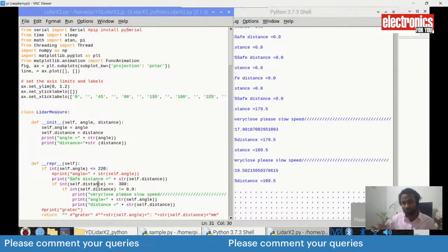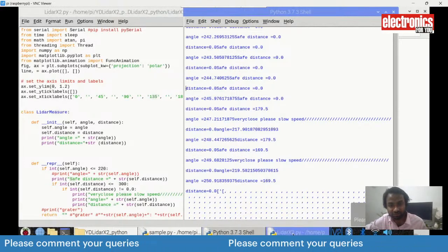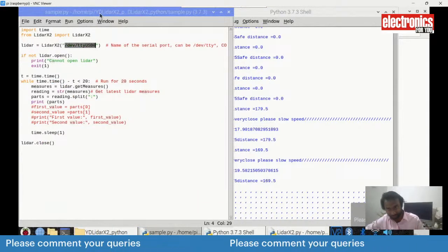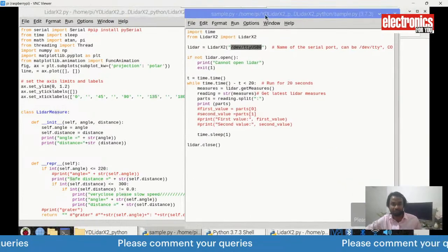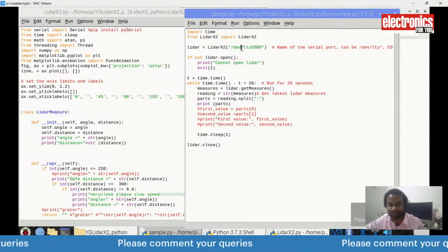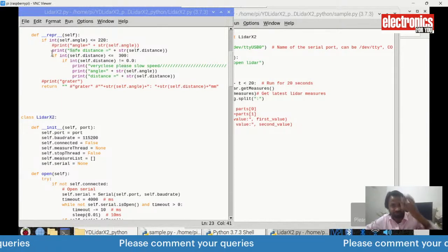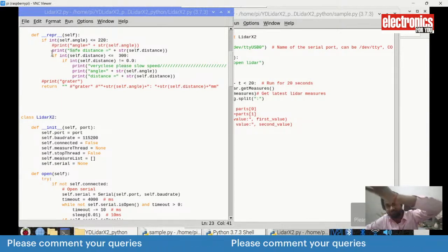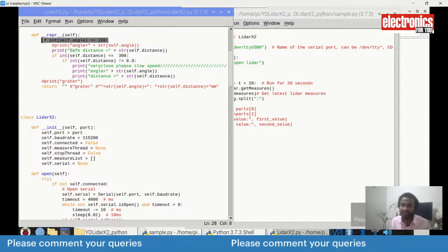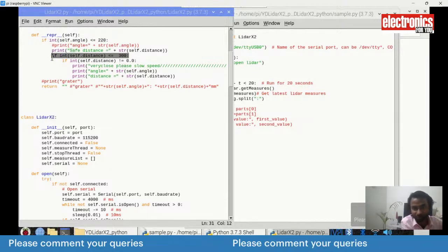So it's on you. What you first need to do is check the baud rate and the USB, then download the SDK of whatever LiDAR you are using, and put that in the code with whatever serial port you have connected the LiDAR to, and then check the speed and distance. If you want to scan only the front side, to 220 degrees from the vehicle, you can set that, and then check the distance, the threshold distance, that safe distance that you want to keep for your vehicle.